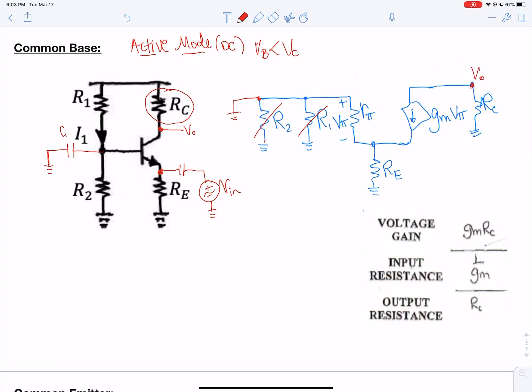So here, when I connect this, I am going to put this right in parallel to the RE, so it's going to bypass the RE itself and go right into that emitter side. And so this is going to be the AC signal that comes in here.